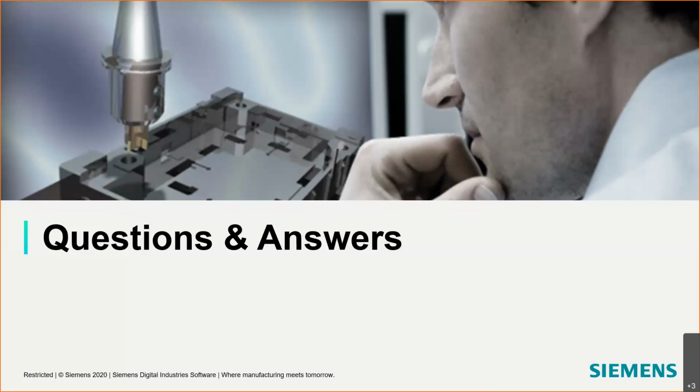Was there any other questions? The first question you answered, Joe, on the tooling: do your tools need to be defined prior to using feature-based machining to identify operations? Yes, I'm not sure if it was answered completely, but you need to define your tool database before, or else NX cannot find tools. If it cannot find tools, you cannot map any operation to the feature.